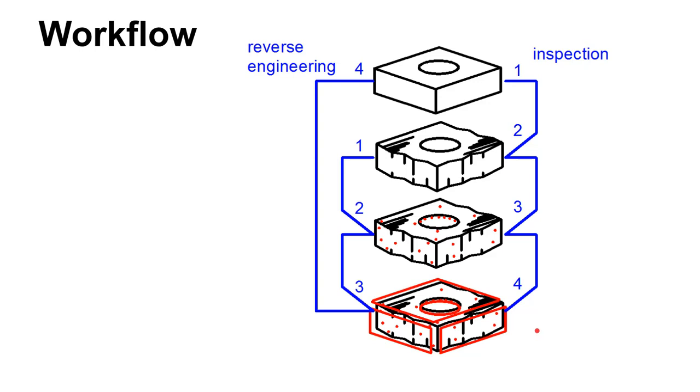What you should realize, a lot of students don't, is that they imagine that if they probe this thing enough it will look like a solid model, and it doesn't really start that way. You wind up with a plane and a plane, but these are generally unbounded planes, and what you have to do is use the information from these to work back if you want to create a model. So if you're reverse engineering, you start with the actual part, you probe it, and you don't get a model down here. You get planes and cylinders, and you have to work the values from that geometry into a CAD model.